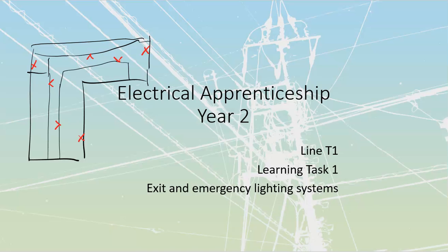What you will see is a bunch of different configurations, but they're all designed to be fail-safe configurations. Which means that if I've got something like a washroom, I'll just draw one in right over here, that's going to be a completely closed-off area. What you'll find is inside of those, you're actually going to have two. You're going to have double heads off of these exit lights so that if any one of them fails, at least that whole area is not going to be dark.